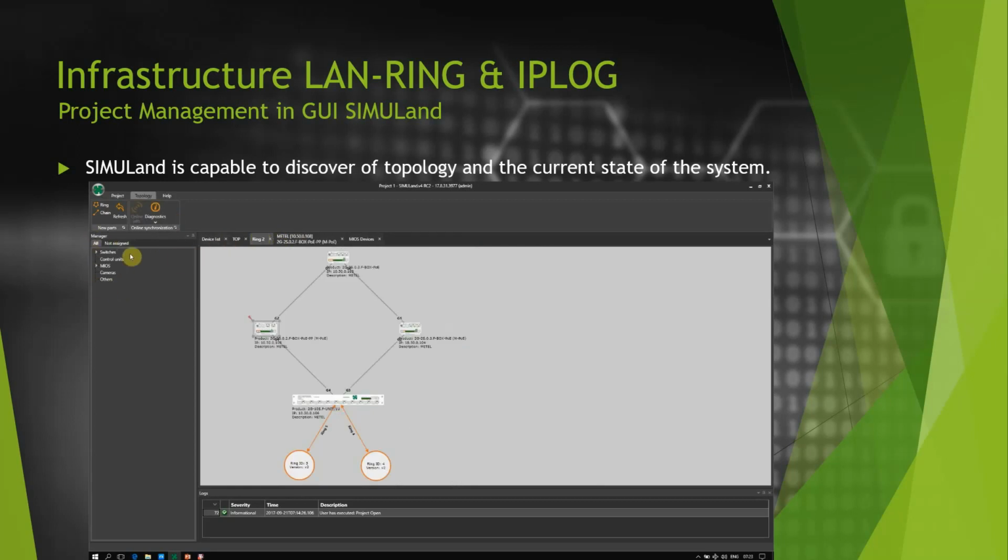On the left-hand side of the screen, there is a manager for organizing objects in the work areas. Under the All tab, all the elements that are included in the project can be found. Under Unassigned can be found all the objects contained in the project, but not assigned to any of the work areas. So if the project contains, for example, a switch with older firmware without LLDP protocol, it will be included there, from which it is possible to drag it to any position.